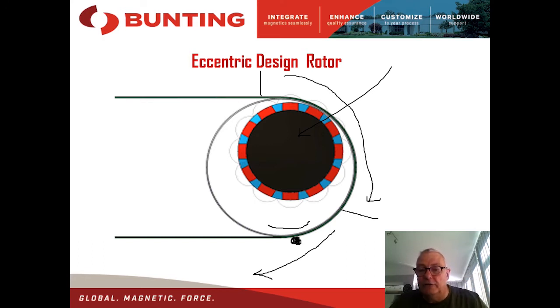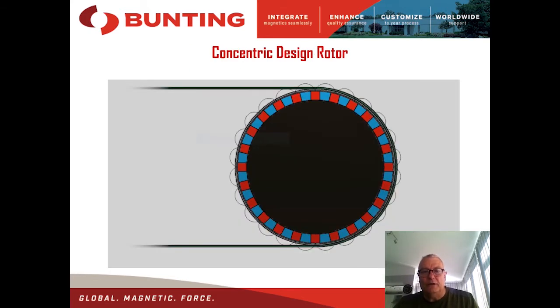There's a trade-off between width of pulley and flexing, as it were. Typically, the eccentric rotor takes up about 2/3 of the total diameter of the unit as a rule of thumb. So eccentric designs are great for some applications. Likewise, concentric designs are great for some as well.